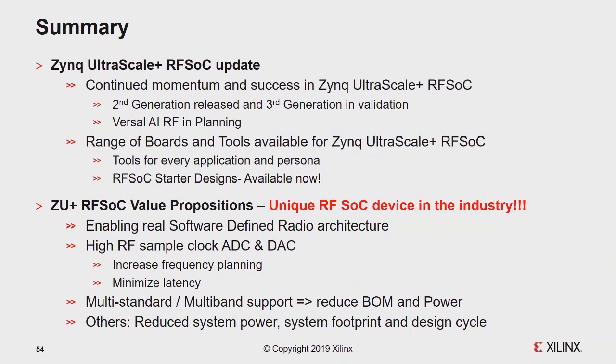And then for my section, we would like to highlight that our RFSoC truly enables the software-defined radio. You can change your configuration through the digital or software. You don't need to do the physical board design on the analog. We would like to make the digital dominant over the analog, so it's easier for you to do production and verification. And then our Gen 3 has higher sampling, so it increases the frequency flexibility and minimizes the latency. And then with multiband, you can build one board to cover all your different configurations.